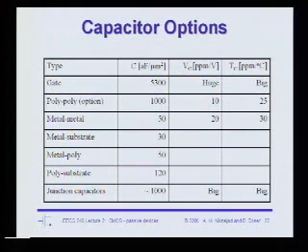Question. Yes. Why is the temperature variation for the gate capacitance big, and how big is it? Yeah, it's because of VT variations. The threshold voltage varies with temperature, and we'll talk about that more next lecture. VT varies, right? Your capacitance varies enormously. It's a good question.